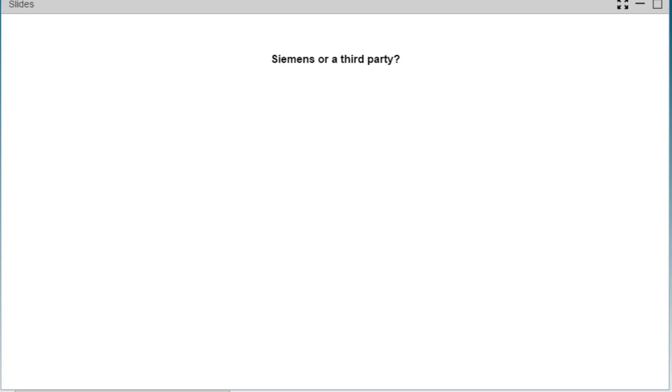So what I would do in that case is have my master CAD, and let's say I'm working with CATIA, and then I'm also working with ProE or NX. One of those would be designated as the master CAD, and the other one would pull the JT data back in. And then from that, I can have reference to those two different CAD pieces in one CAD system. I can create my drawings. There are tools within Teamcenter as well where I can create drawings from JT data.